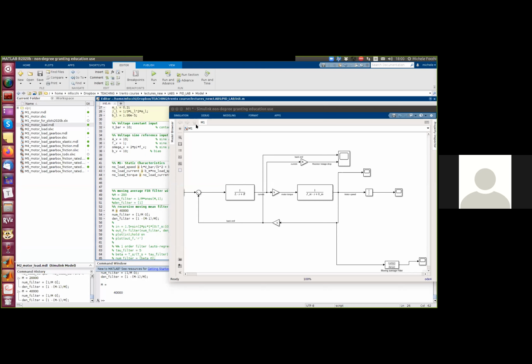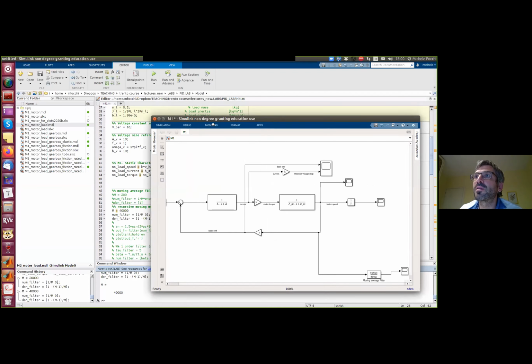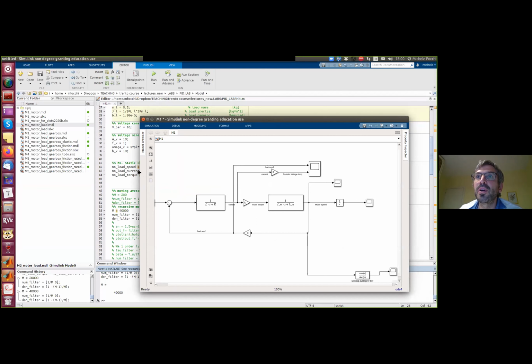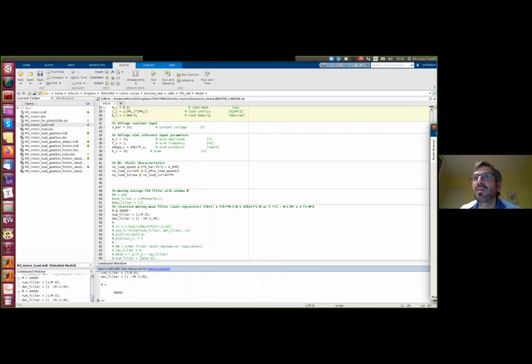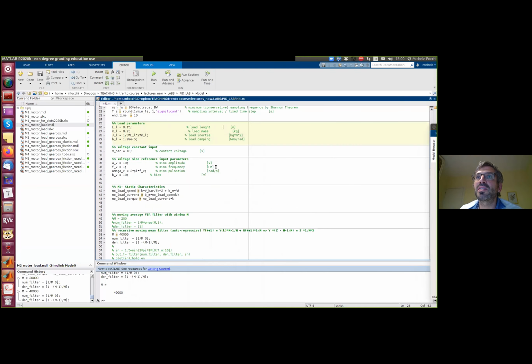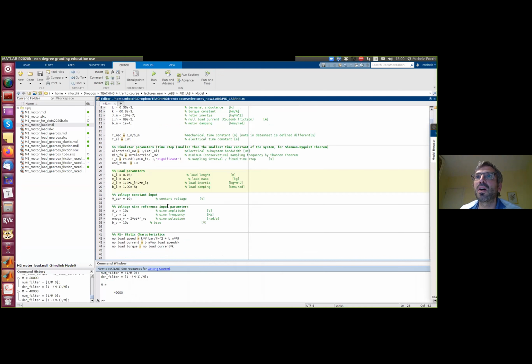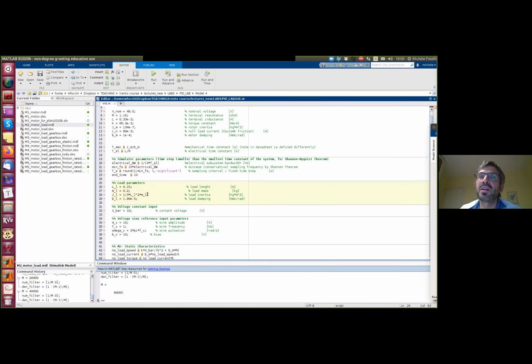Yes. Okay, so now let's try to solve assignment 2, which is adding a load. What does adding a load mean? Since we have no gearbox and no compliance, it means just summing up the inertia and viscous friction values of the rod we added. So we have the parameters of the load, let's say 15 centimeter length, and mass.